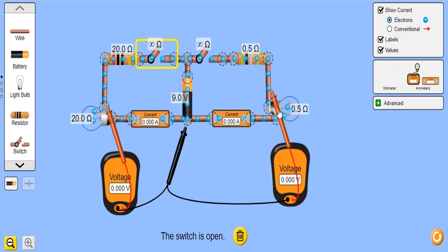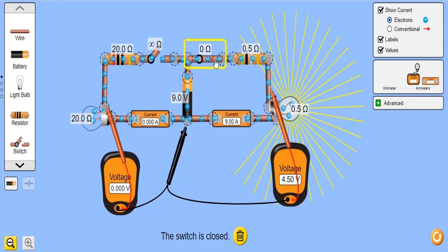One more thing you need to pay attention to about resistors. That is the power consumed by the resistor. I have 2 circuits with the same voltage divider, 4.5 volts. But the circuit on the right will consume more power. So the resistor in this position needs to have a large capacity, or it will burn out.